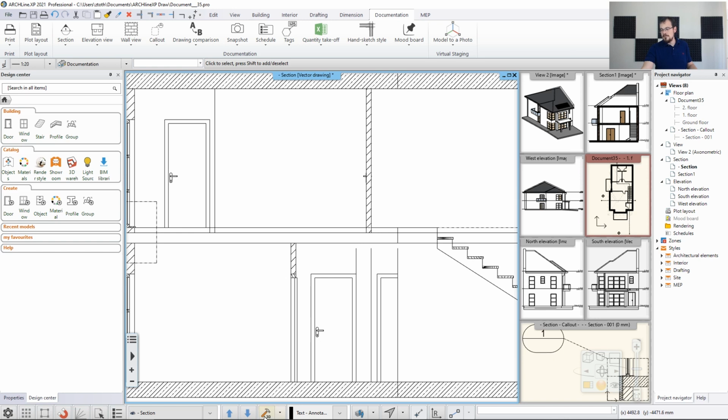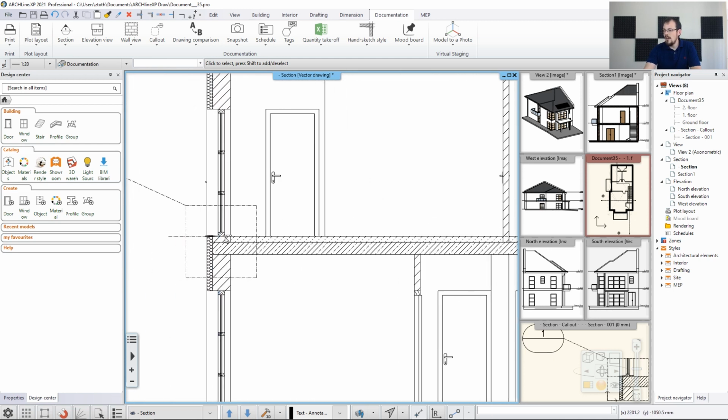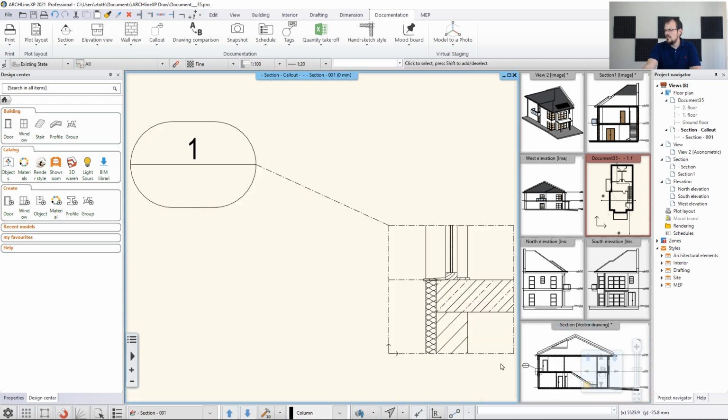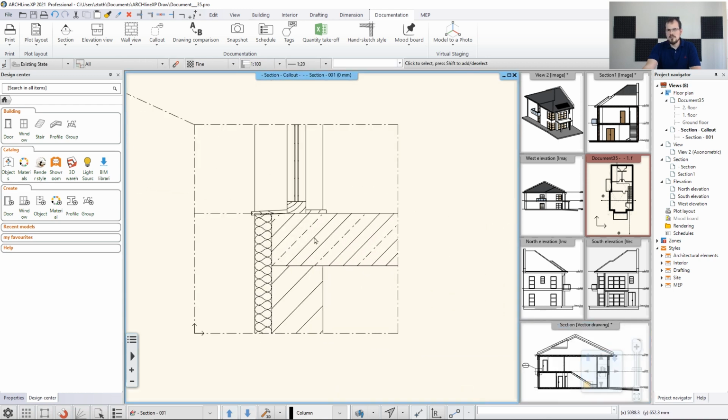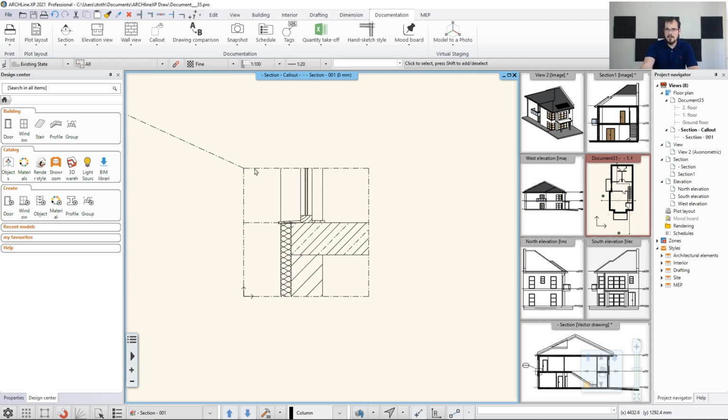We have to rebuild the 3D again to make sure that it's actually at the right place. And then we see that all the interactions are okay. So here we have the interaction just fine, and here we have another one. Last thing we have to do, we have to make sure that these changes are reflected on the callout, because on the callout we still only have one layer, so this is not the end result. The end result would be nice 2-layer structure with the floor, with the slabs and the walls meeting with each other the right way. So it's simple to do it.